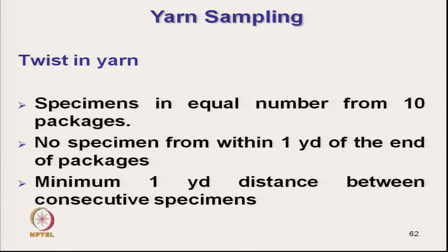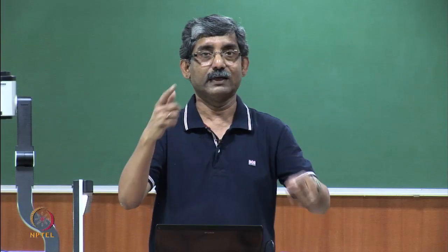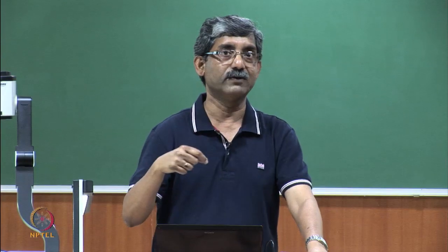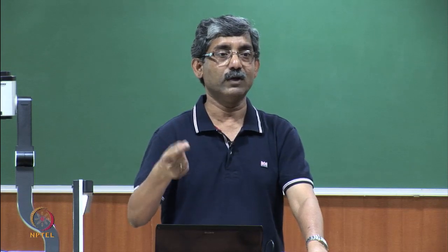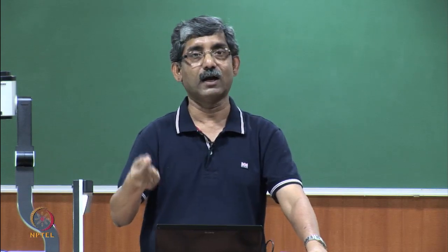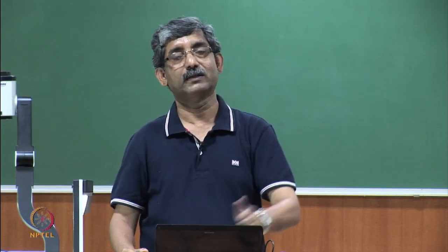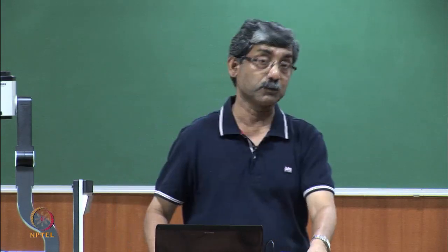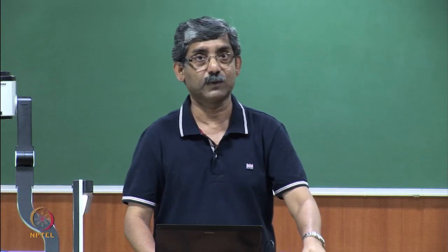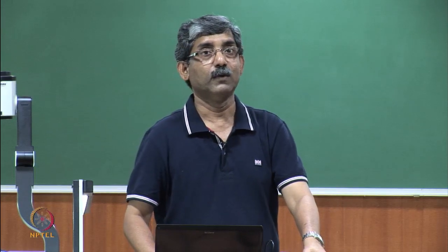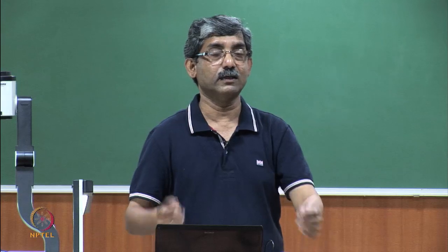Otherwise, what will happen? Twisted material will always have a natural tendency to get untwisted from the end point. So, just to eliminate this possibility, we have to take this precaution, because if the twist is getting untwisted, then we will get a wrong result in the twist measurement.